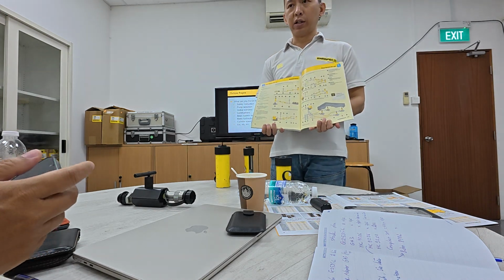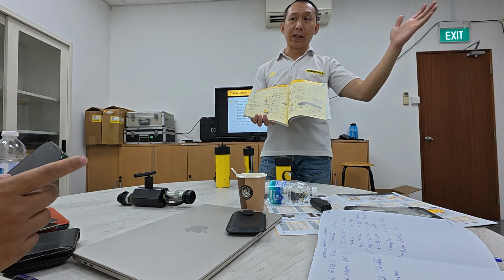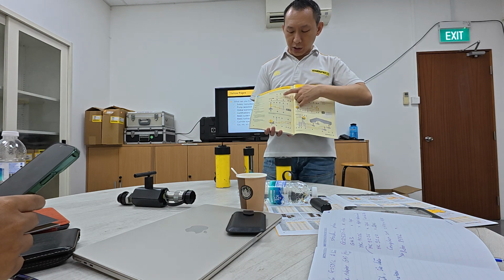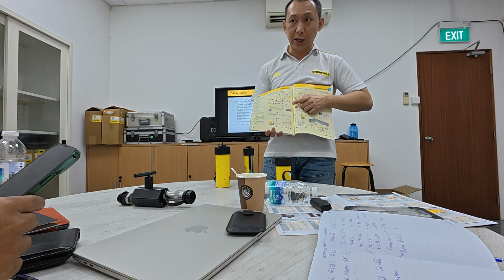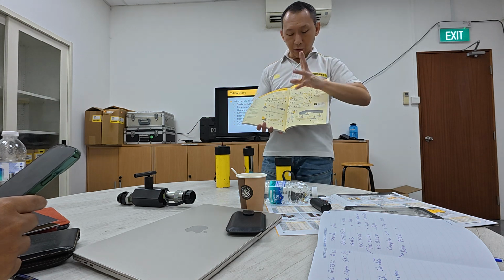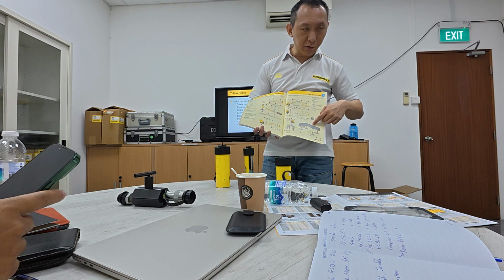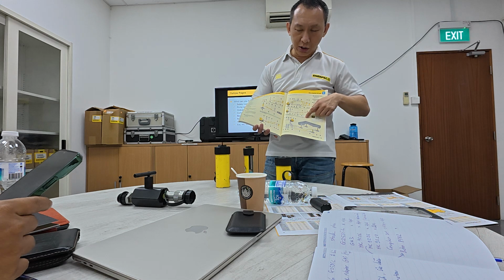If the customer cannot visualize what the setup is like, just show them this page. One pump per cylinder, how you set up a gauge adapter, this is how you set up. If they want one pump to four cylinders, this is how they should set up. The four cylinders, gauge, manifold, gauge, this is how they should set up.